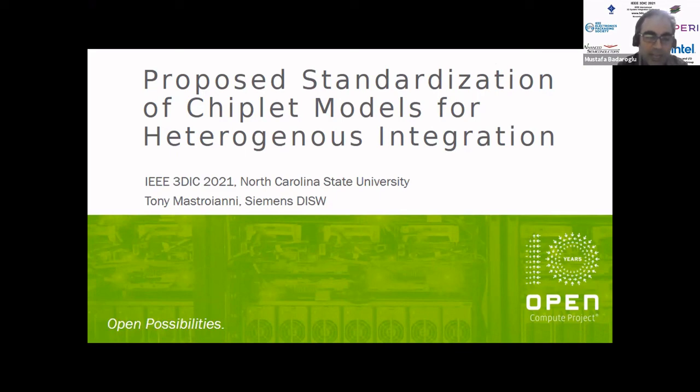But afterwards, if it becomes a 2D channel for a gate-all-around device, then we need to think about it, because there the layer transfer technology will not work because it will become too expensive, because you need a lot of 2D channel material layers, or some kind of a spatial epi-like growth enablement necessary if you want to go for monolithic integration of 2D. Yeah, thank you so much.